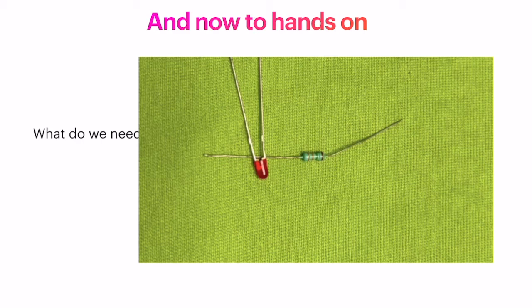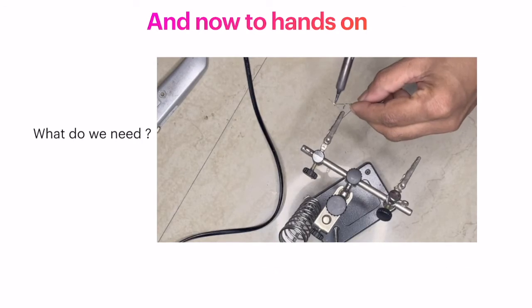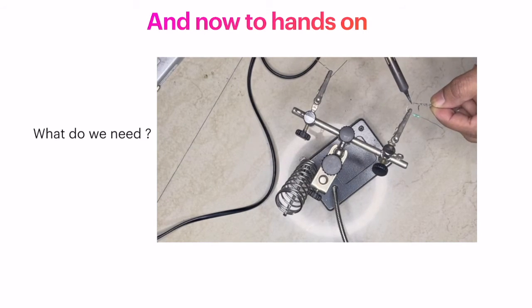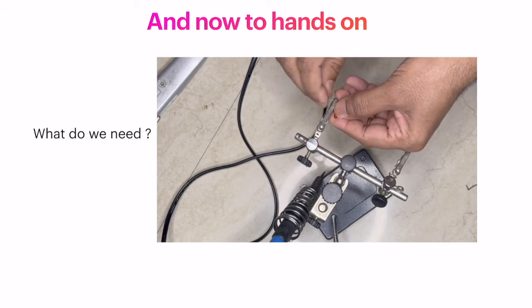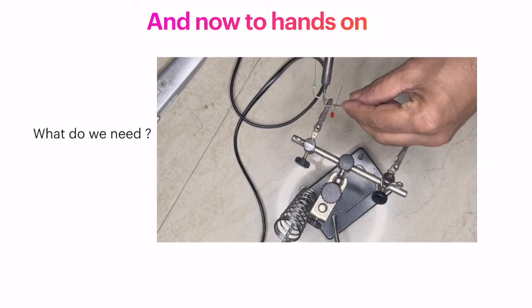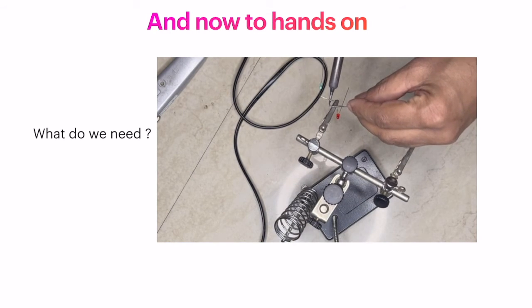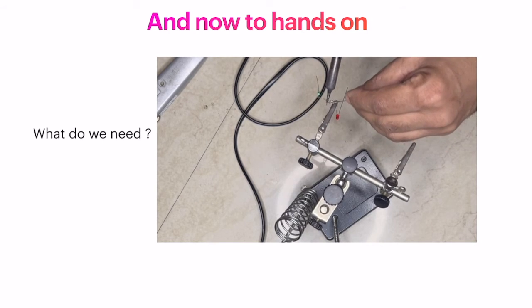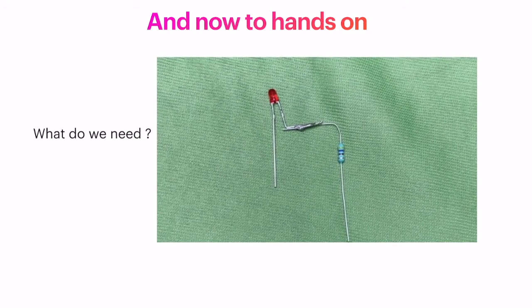Of course, to control, we need a standard LED with a resistance of around 300 to 400 ohms, which would be enough to reduce the voltage from 5 volts, which is usually digital high, to the operating voltage of the LED, about 2 to 3 volts. We can solder this together for neat work. If you think your digital soul is not agreeing with soldering, you can simply twist the wires around. You can see that I am not very good at soldering, but some small soldering can be easily done, and the end product would look reasonably good, as you can see here.